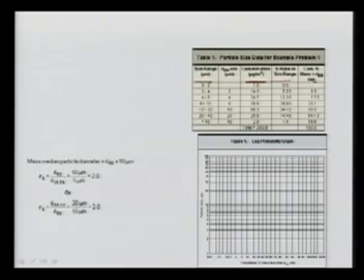So, between the particle size, let us say 2 and 4, the minimum diameter was 2. The concentration in the particle size range 2 to 4 was 14.5, and the mass of the particles in this size range was 7.25, as it was the percentage mass. So the cumulative mass was 0.5, and all the cumulative masses are shown here. They will increase and finally should add up to 100.